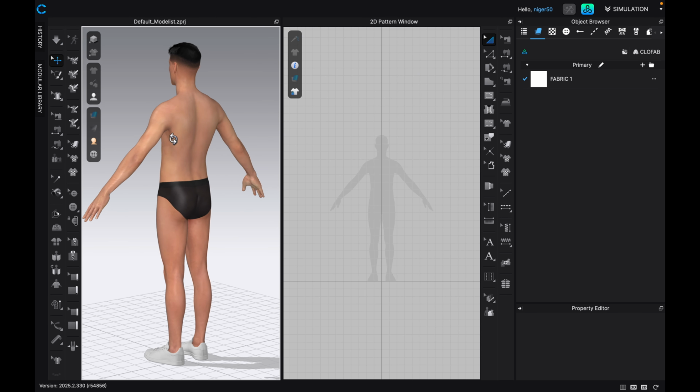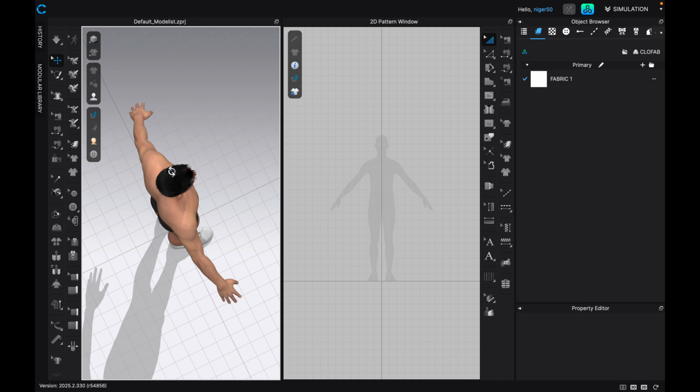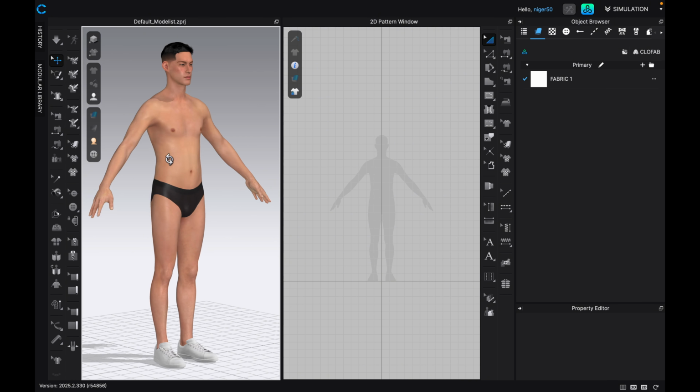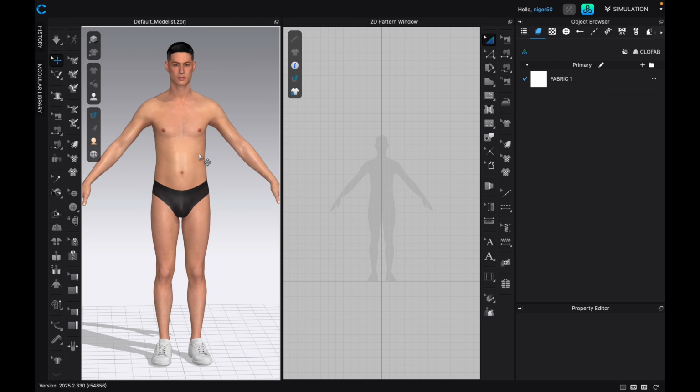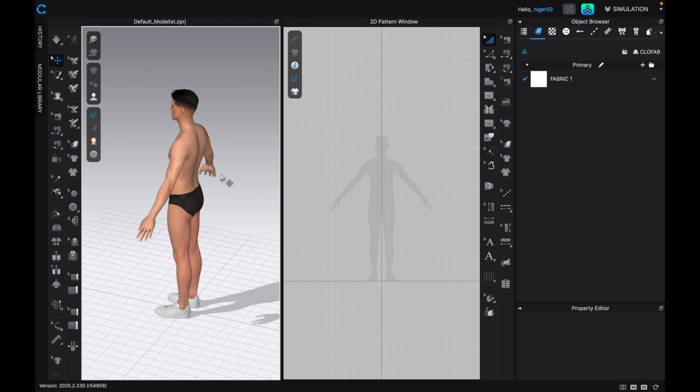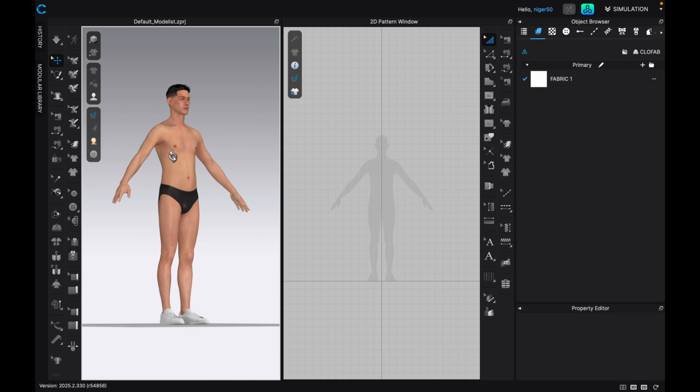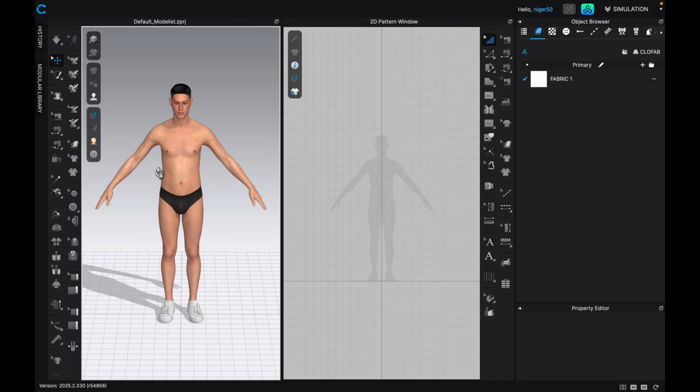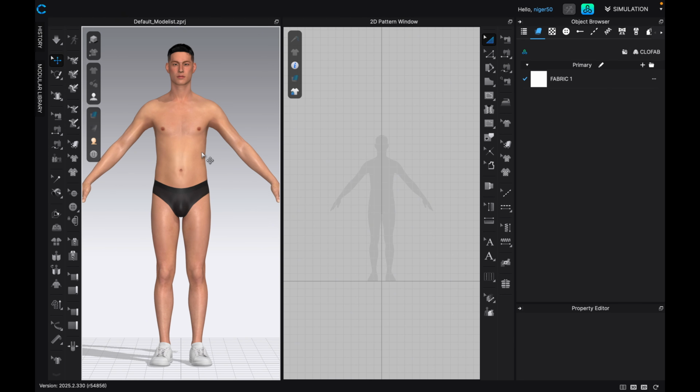There's another important thing, that is the scroll wheel. You can use the scroll wheel to zoom in and zoom out. Use the left click and Alt to pan around, or you can also use the Option key and left click to pan around. Both are the same thing. So let's press 2 to go back to our normal view and start the project.